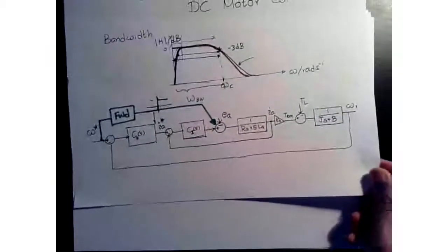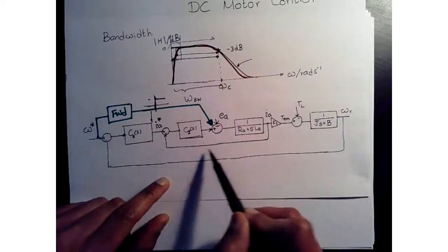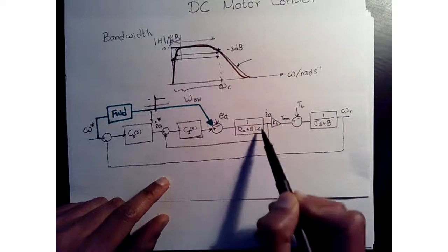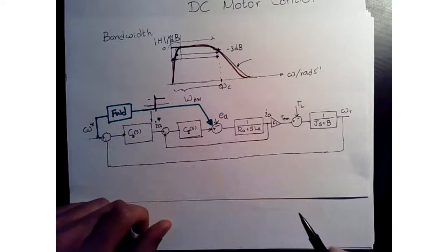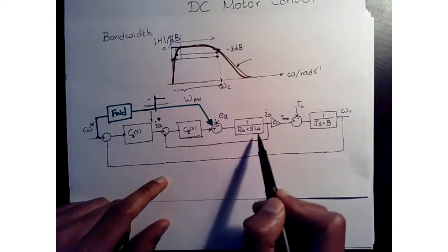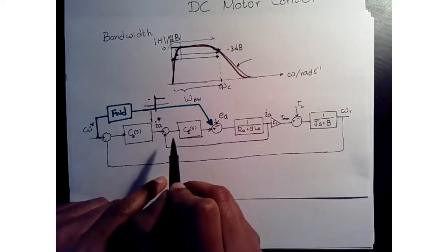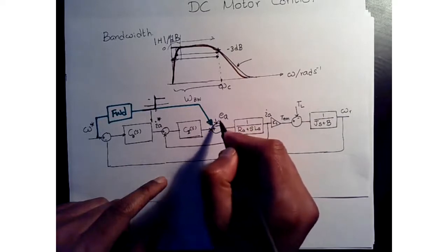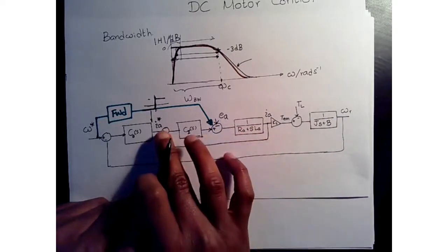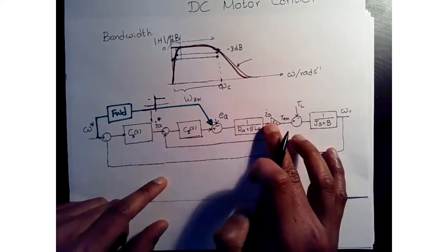Now, let's go back to our original diagram here, right? So we basically designed our control loop, our closed loop system, to control current. So when we do that, now we have a very nice control for that loop. Okay, and then for the locked rotor case, if we set our back EMF to 0, then what can we say about IA, the reference, and IA?